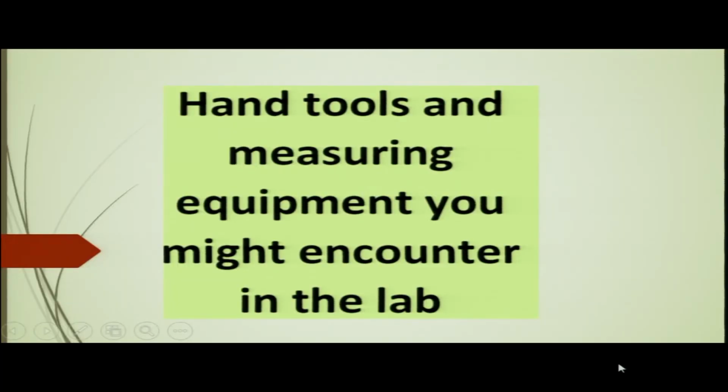You can also see this in many pull-up doors, for example: if you pull the door from the top, at any level it can stay, and it will not go back if you leave it. So, these are the worm and worm gear, also used where you need very high torque to be transmitted. These are basically the transmissions that I wanted to tell you, and through these mechanisms, mostly in mechanical engineering, the power is transmitted from the input shaft to the output shaft.